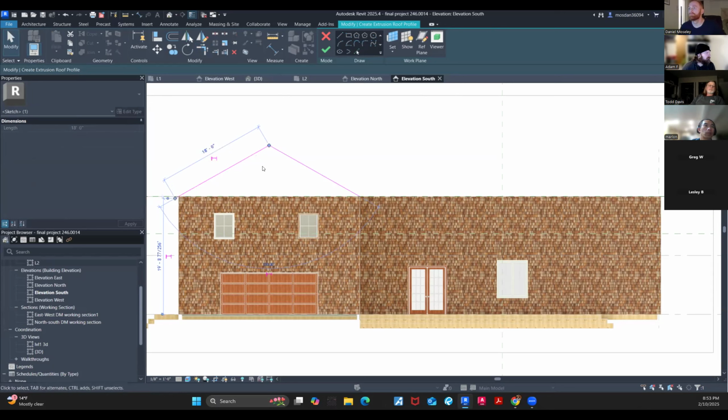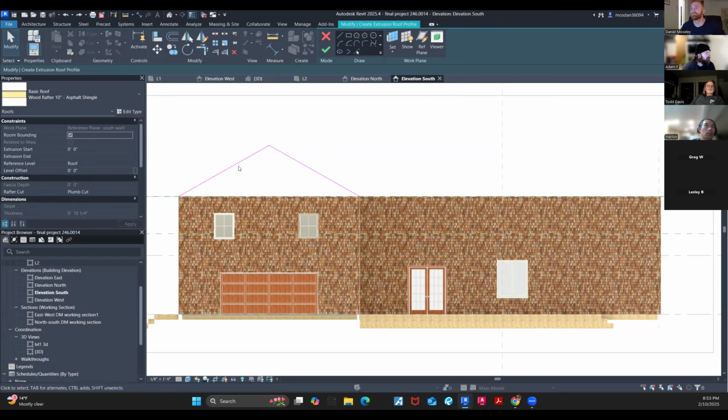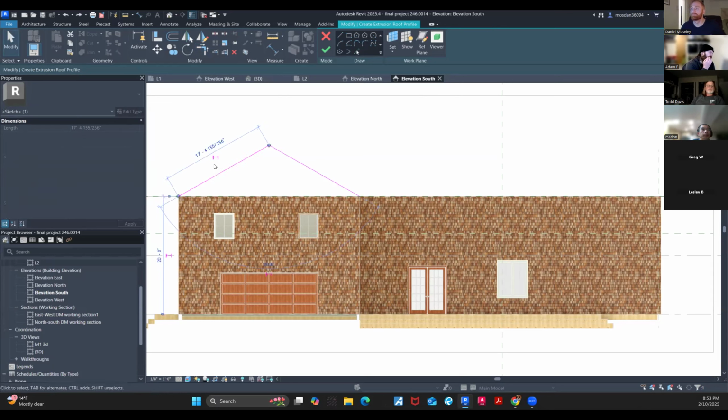Oh, no, sorry. Hit Control Z. Grab that. Make it 18 foot 4 and whatever. Add a full foot to it. Oh yeah. Okay. So nope. Sorry. Hit escape again. Click. It's okay. This is good. Click into it. Click into it again, right where the 7 is. Delete the 7 and type in an 8. Okay, you now made that a foot longer. Hit OK. Since it's joined at the middle, it's not going to change.